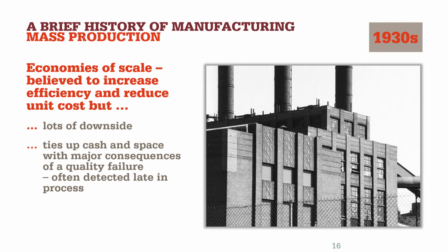In those days there was a long changeover time between one operation and another, therefore changing machines to produce different products actually consumed a lot of time, which is what drove the idea of large batches. And as I say, as long as everybody was buying cars the same, the cost effect of that was relatively small and the economy of scale was valuable.